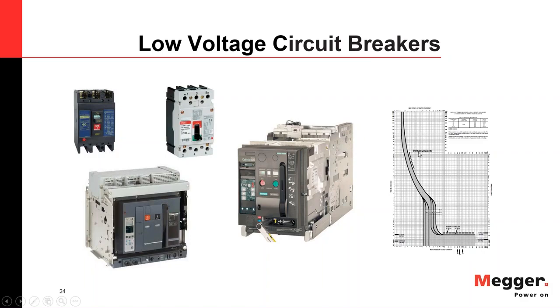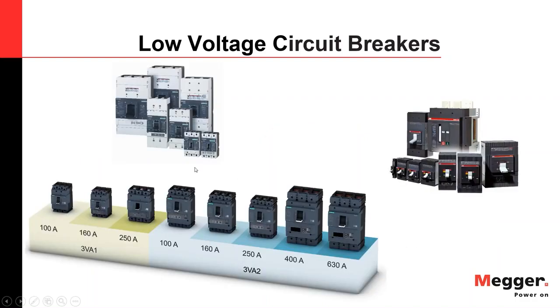And these trip units have curves, and I put one example on the right. So these curves look more or less the same, and this is the specific case for the low voltage circuit breakers. Then they come in different sizes, different manufacturers, ABB, Siemens, Eaton, and they can go up to 600 volts, 690 volts. Then they, of course, grow bigger in size as well, because you need the isolation distance.